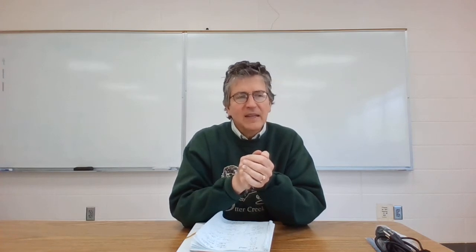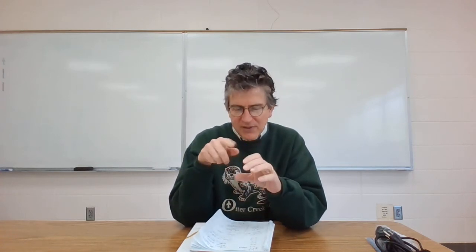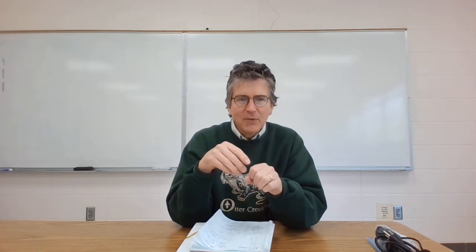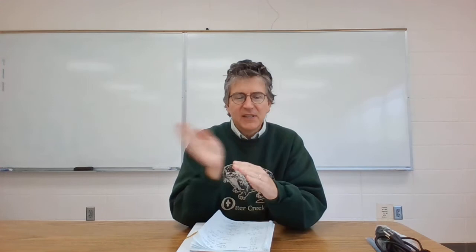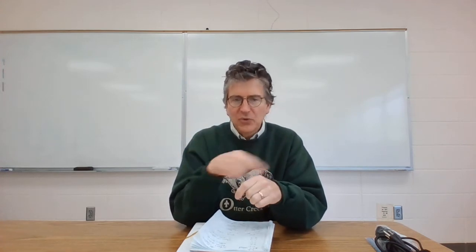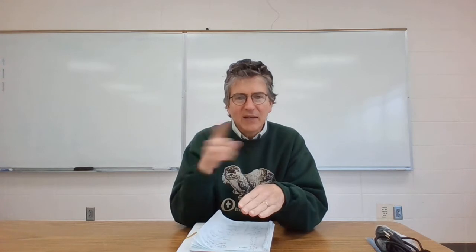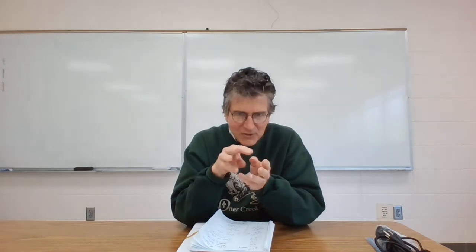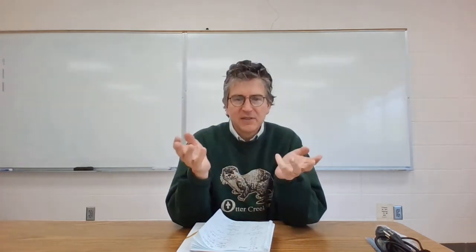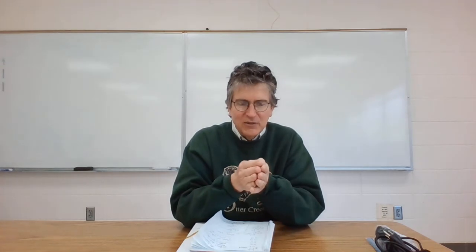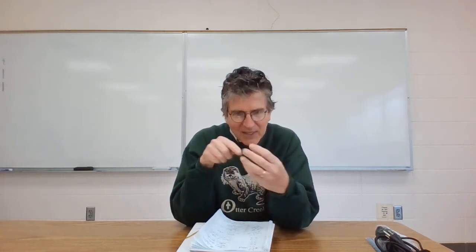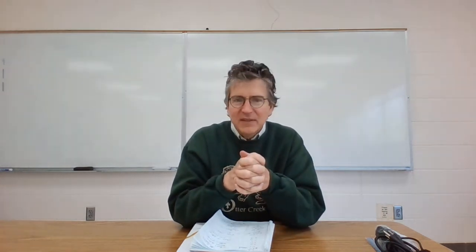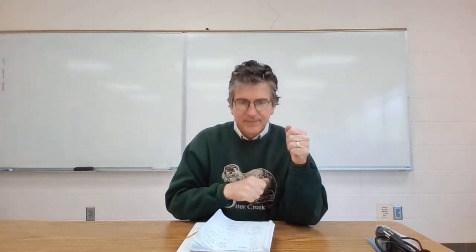If I didn't have those brushes, that commutator arrangement there, what I would have is an AC current. The natural thing that you're going to generate from a rotating motion is an AC current. So you don't need as much mechanical switching, or you could do some sort of electronic thing. But traditionally you don't need all that mechanical doodah to keep switching the current and maintaining a direction. So that's a big difference between AC and DC in motors and generators.